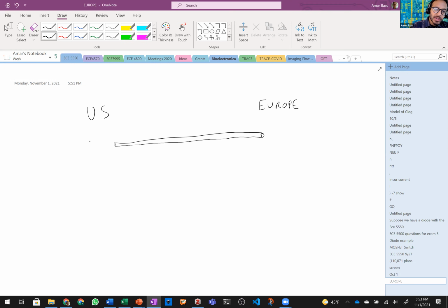And the way fiber optic communications work is you have laser diodes or LEDs, light emitting diodes. So these are both based on diodes. These send pulses of light in certain patterns down these fiber optic cables. And on this side, the symbol is a diode. When you pulse current through this diode, these diodes convert the current to light. And so they send pulses of light down this cable.